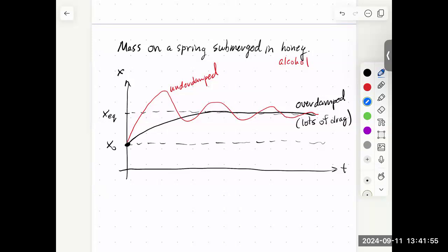So you're going to be constantly changing the temperature of your sample using these control systems. Your control system can be underdamped and it'll oscillate about the new equilibrium temperature before finally settling on it. It could be overdamped, where it takes a long time to approach that equilibrium, or it could be critically damped, where you quickly reach that new equilibrium in an optimal least amount of time, and that's called critical damping.